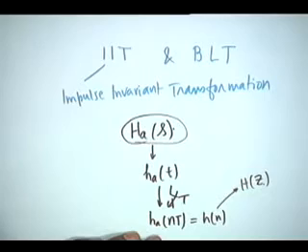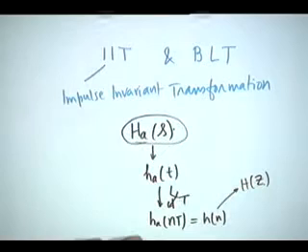No transfer function can stop abruptly at a particular point, because it would disobey the fundamental Paley-Wiener criterion. They would be non-causal also, that is, unrealizable. So, no transfer function is band limited, which means that some amount of aliasing distortion is bound to occur. So long as you contain this within tolerable limits, it is perfectly all right.